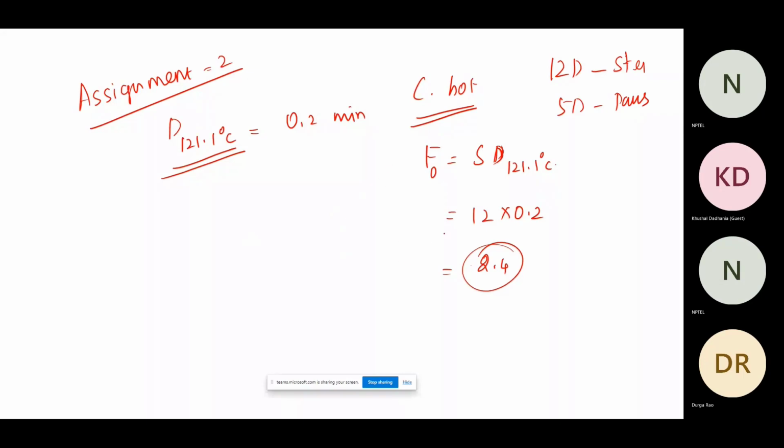Sometimes it happens, for example, if you are having m, Cp, del T, and so on. Just now we had seen that you were asked to find the mass flow rate of the water. If I am finding it directly, I'll take the mass flow rate of milk times Cp del T of milk divided by Cp del T of water.